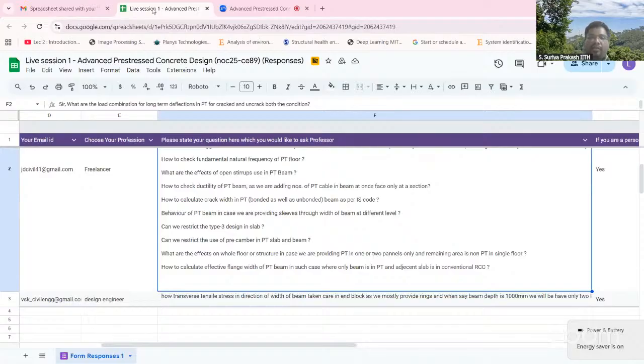Well, wherever you have PT, the beneficial effect of pre-stressing will be there. But as a whole system, the amount of reinforcement we are adding to the concrete, by volume, is not more than 1%. So whether you're doing PT or not, the overall structural behavior, let's say your vibration characteristics, is not really going to change. PT is only for the localized element behavior.